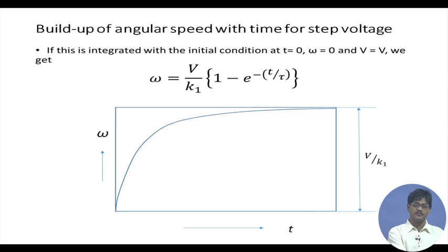represents the time response of the system to an input. If this is low, we have a very fast response, and if this is high, we have a sluggish response, and we always want the response to be as fast as possible, barring the case that it overshoots. That is, it should not overshoot, but it should be as fast as possible.